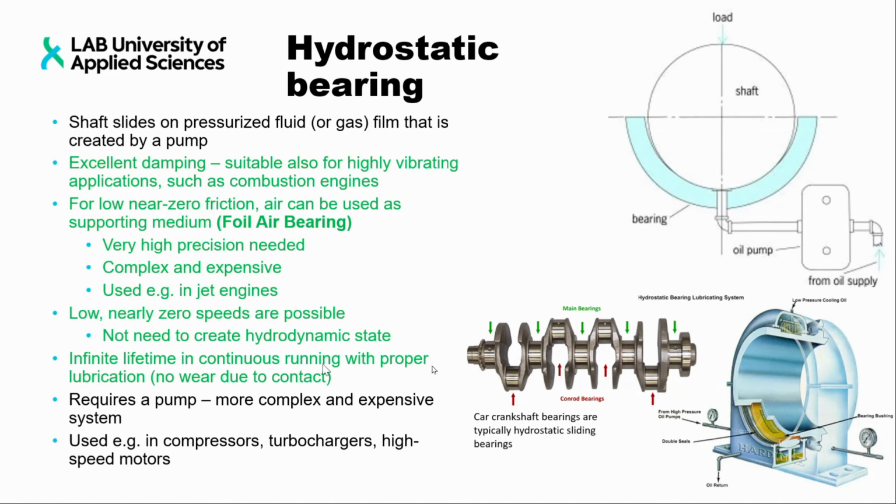But of course, again, it requires a pump, and the pump has to be a fairly high capacity pump, so that it is able to produce the high pressure, and it requires that the system is a bit more complex, and it's a bit more expensive. But they are being used, for example, in compressors, turbochargers, high-speed motors. By the way, turbocharger bearings are this kind of bearings as well.